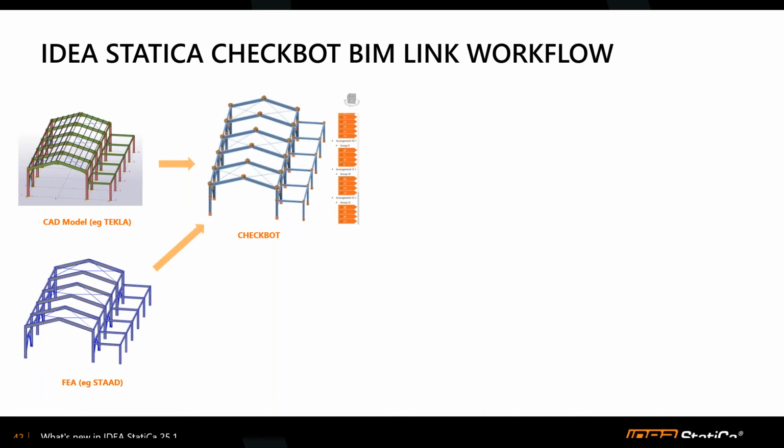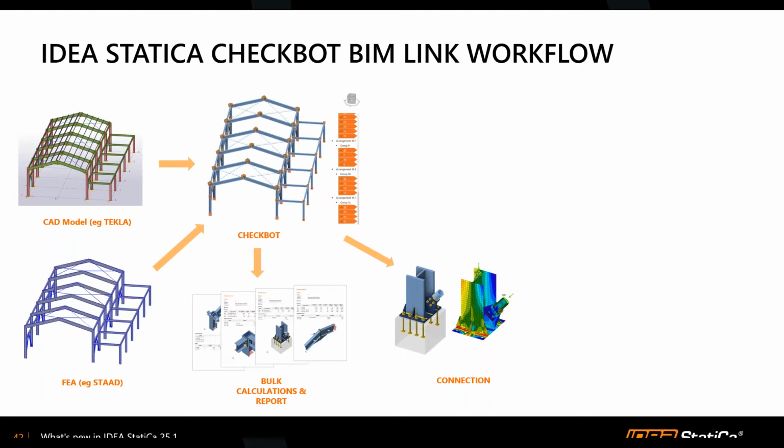When you design the joint connections by modeling them with the required manufacturing operations, you can then run the analysis using bulk calculations, and also generate a bulk report for all the connections. And if you want to verify further for the anchoring, you can also export it directly to Detail 3D for verification, which includes the reinforcement, of course, for the concrete block.